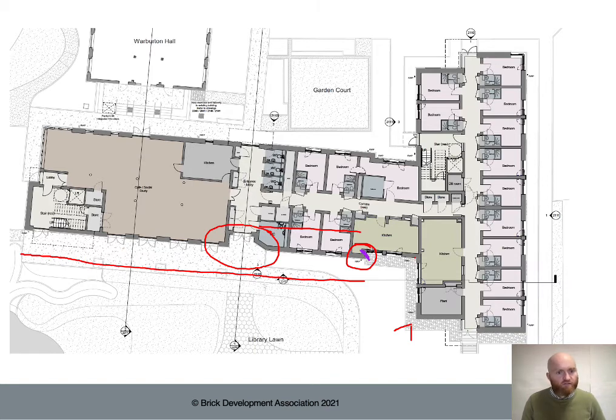If it is, then fine, we don't need a movement joint in that area. If it isn't, then maybe we do. We've got the recess here. Actually, let's check that. Is that less than 675? If it is, then maybe we need a movement joint. If it isn't, then we won't. And then the next section, again, that looks like it's going to be longer than 6 meters.